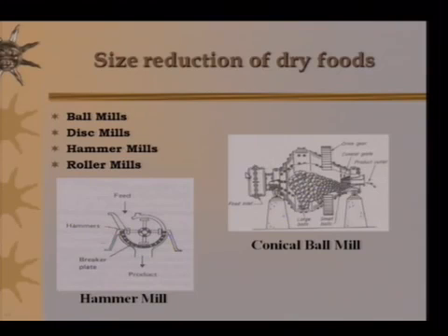They vary from mill to mill, but their sizes are different. The material feed inlet is here at this point, and then the material goes inside the mill, where there are large size balls in the center and small size balls on the right hand corner. Now the material gets crushed by the balls, and ultimately it becomes a fine material and comes out from this point. The whole machine is driven with the help of a motor and a drive gear which is attached to this motor. There are larger balls and smaller balls which do the operation.